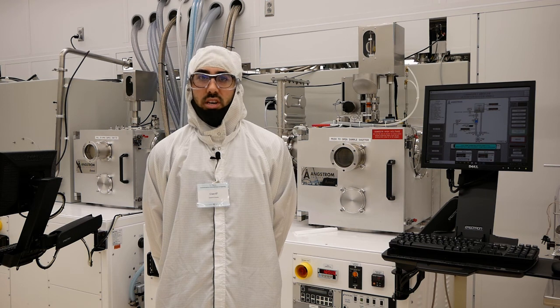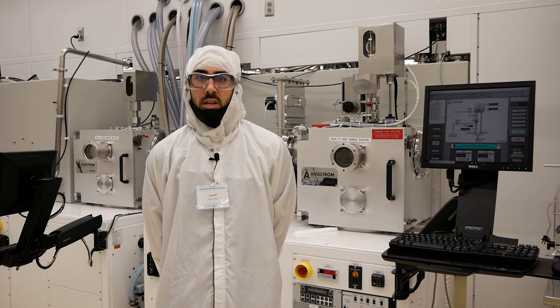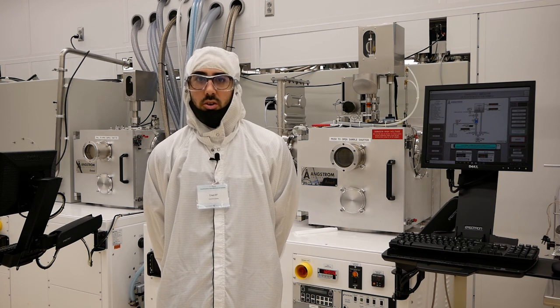Hi, my name is Alberto. I am a graduate student in the Lee Lab at Vanderbilt University. I use the VINSE cleanroom to fabricate retina-on-a-chip devices, which are microelectromechanical systems using lithography, deposition, and etching of the materials polyimide, gold, SU8, and PDMS. These have applications to study the neuron connections in retina, which will help us understand better how intracellular communication works.